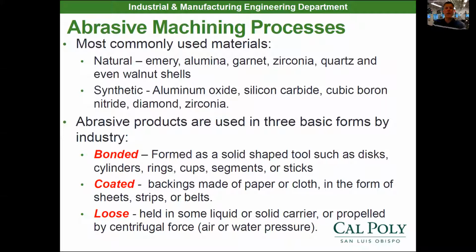Some other ones that you saw last week, we used garnet, right? The garnet was a natural abrasive found on the earth. We just take that garnet and put it through a sieve system. A sieve is a collection of fine mesh screens, so you can get the same exact size abrasive particle out for every single particle. They use sieves to get the natural abrasives to the right grit size, because if you remember, they're sized by grit. We'll talk about that again here in a second.